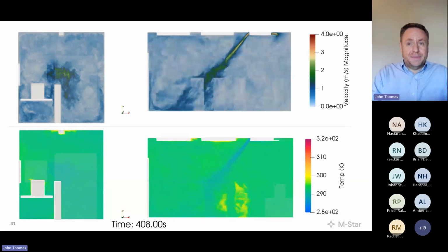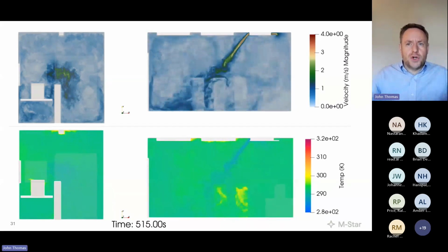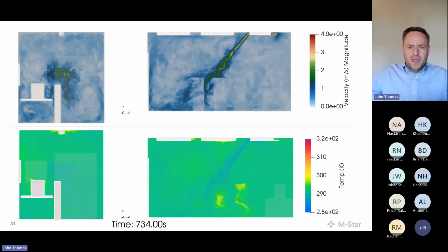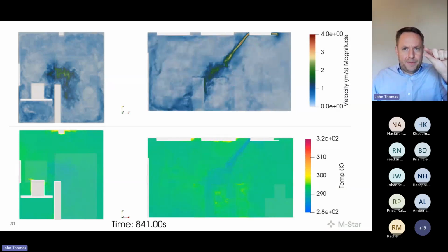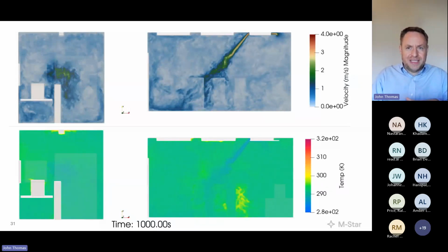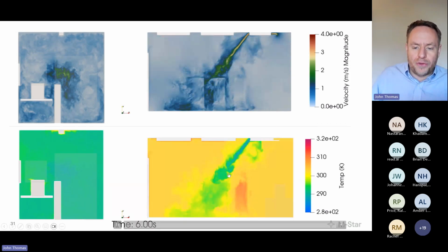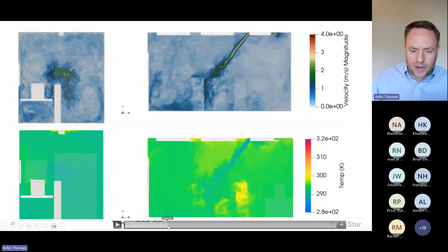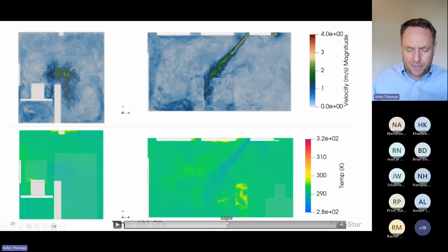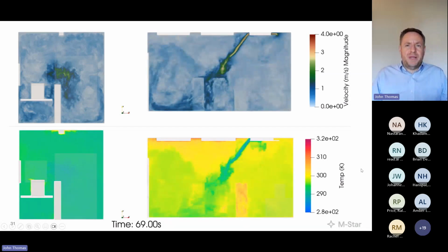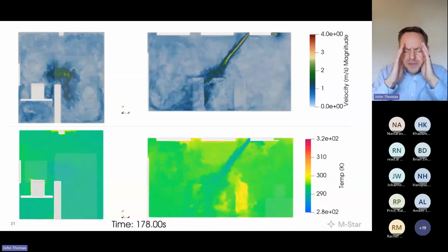Said again, on my laptop, these long-term processes where we're coupling tens of minutes to hours of flow simulation with a millisecond time step informing the creation, the destruction, the advection of individual eddies, breaching those timescales, that's in play on a GPU, right? Looking at how the temperature evolves, how the initial splash of cool air competes with the initial temperature and the ongoing thermal convection from the people and the computers, etc., and watching how it eventually cools off over this 1,000-second interval, that's in play.